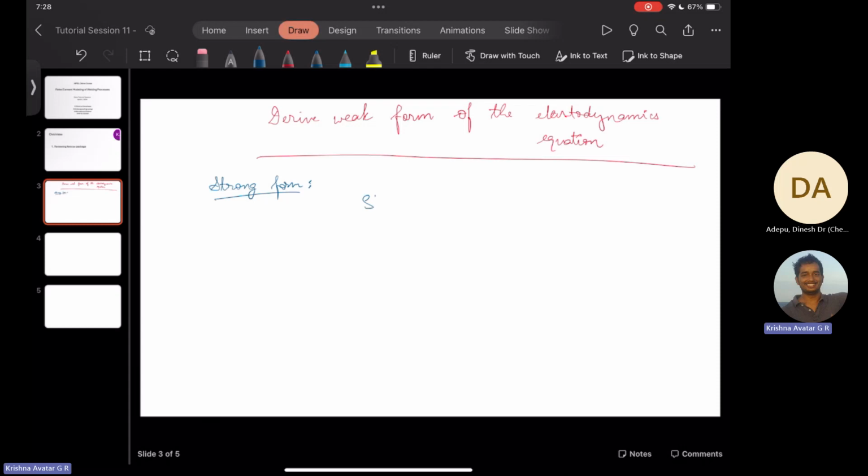So the strong form is rho u vector double dot is equal to divergence of sigma plus rho f vector. Now you'll see that this equation is valid for any material eventually, because this follows from the balance of linear momentum for any body, any body. And then to complete the problem, say given this arbitrary body with volume omega and the surface being